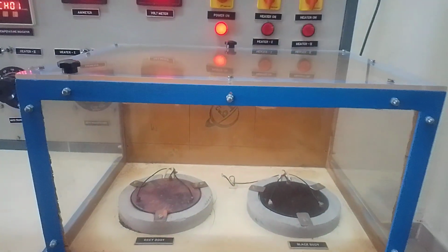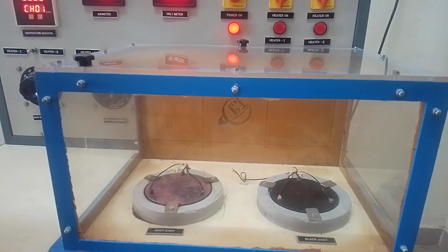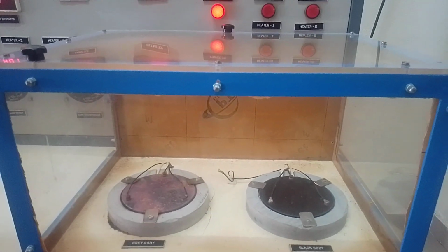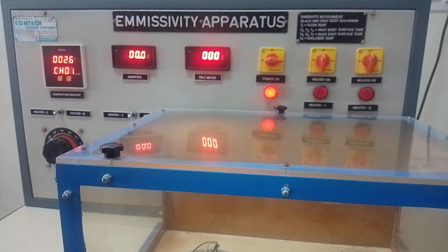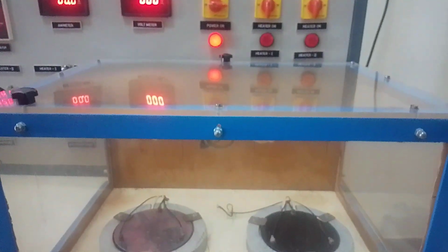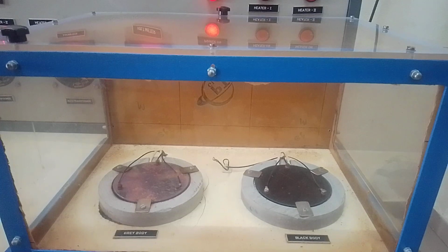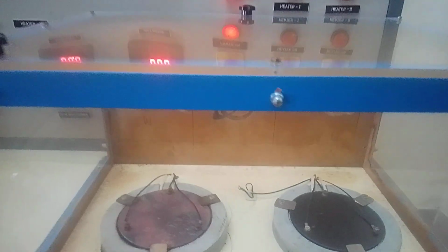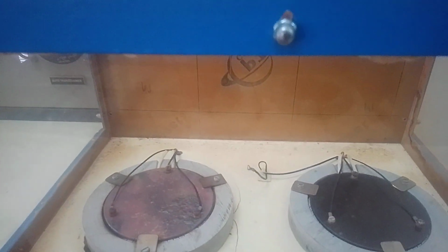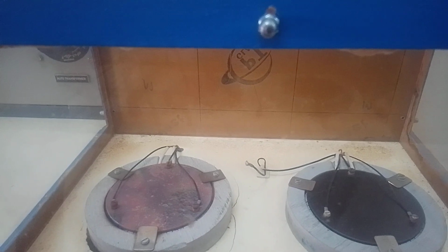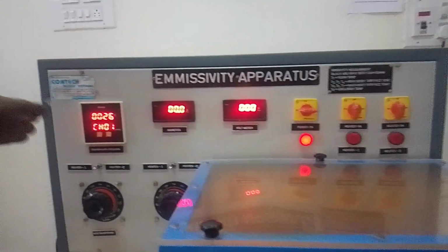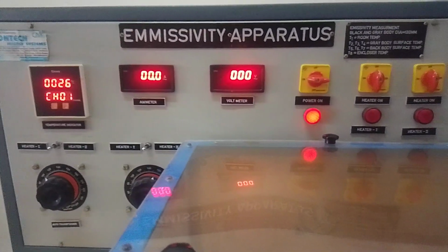The temperature of the plate is measured by thermocouples. Separate wires are connected to diametrically opposite points to get the average surface temperature of the plate. Another thermocouple is kept in the enclosure to read the ambient temperature. A digital voltmeter and ammeter are provided to measure the heat input given to the plate. Whatever thermocouples you can see attached are connected with wires. We are not able to see the thermocouples on the surfaces, but they are connected with this connection to find out on the indicators the temperature at the surfaces and the ambient.